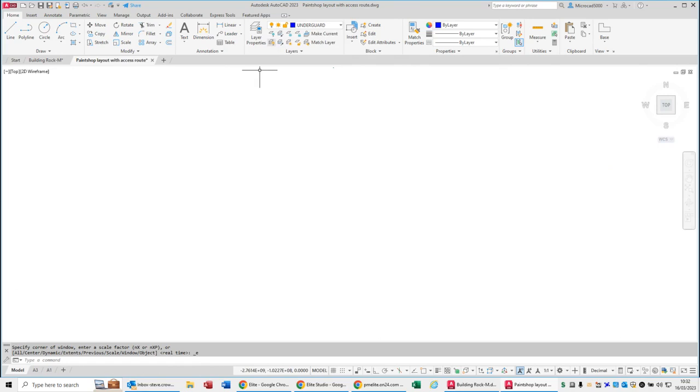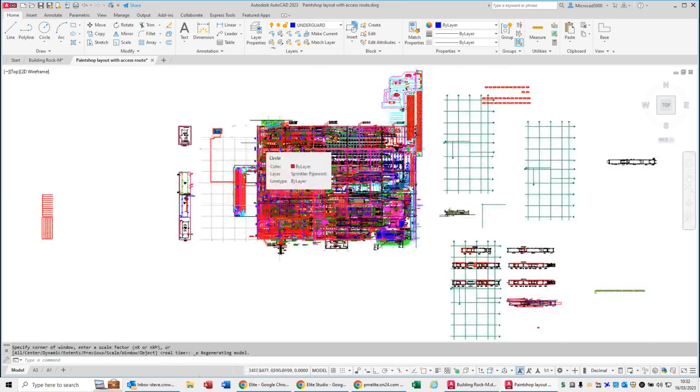I want to use this button here, look. Turn all my layers on, quick and easy. And there it is, look. In that key that we saw earlier on, there's some hatching in the boxes. And there it is. Now, this blue grip over here is not an object. This is the origin of the hatching. So if I delete that hatching, double click my roller, there we go. Now we can see the complete drawing, and that drawing's been fixed.